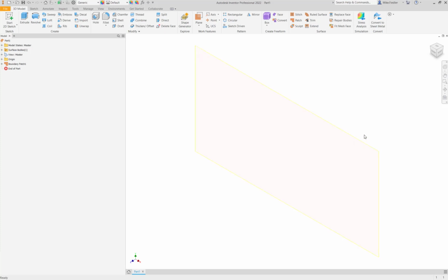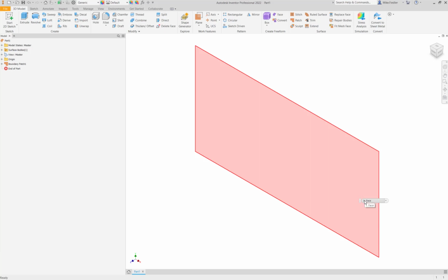We could make this 6 inches long, 3 inches tall, make it a quarter inch thick, and then when we get into the Nastran environment, we can use the tools there to collapse it down to its mid-surface. But that's really just creating, in this case, since we're starting from scratch, some extra work for ourselves. But please be aware, and I've shown it in some other videos in Nastran when we're working with shells, that if somebody hands you a model and it's a thin, solid body, you certainly can collapse it down to the mid-surface if you ultimately want to analyze using shell elements. But again, since we're starting from scratch, may as well just make it out of surface geometry.